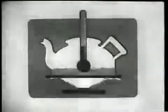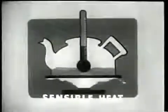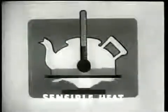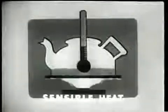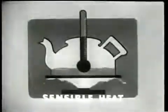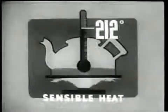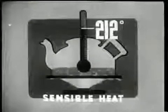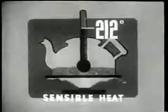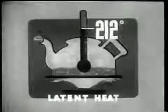Of the three effects of heat, refrigeration is chiefly concerned with two. The first effect, that of sensible heat, is one that causes a change in temperature as read in degrees on a thermometer. In this example, as heat is applied, the temperature of the water in the kettle rises up to 212 degrees Fahrenheit at sea level. At this point, the temperature remains constant, and the second effect, latent heat, is observed. The water changes state and becomes a vapor.